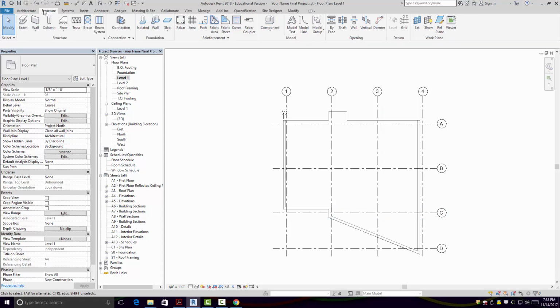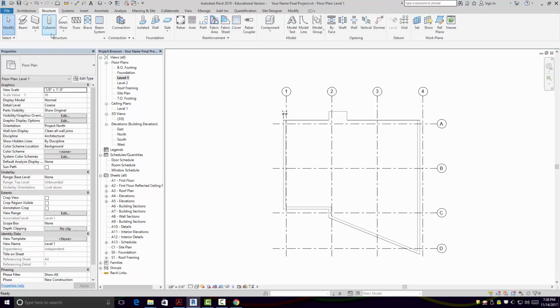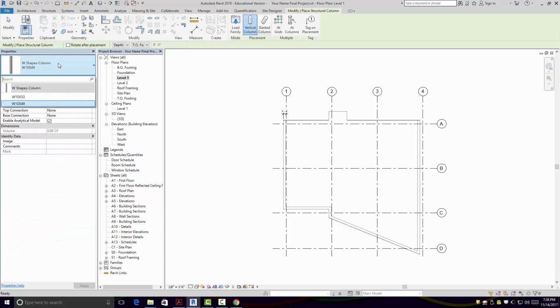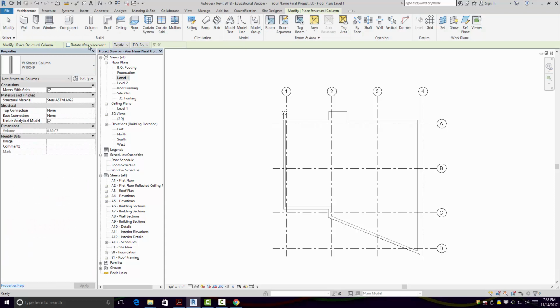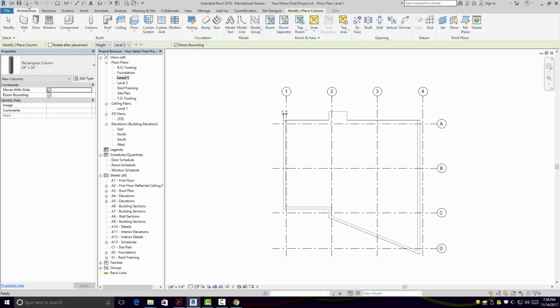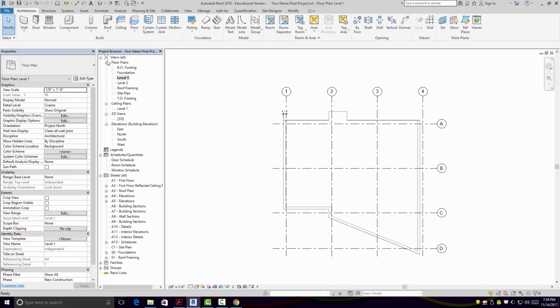Later on, you're going to put a column on it. So in this case, instead of using a W section, we're going to use a pipe column. So I don't think there should be one loaded in here. I thought I think that's actually an architectural column. Nope. Okay, so not on the commercial template. I'm confusing myself with the other template. All right. I'm sorry. Yeah, so I'll have to go to the Imperial Library.